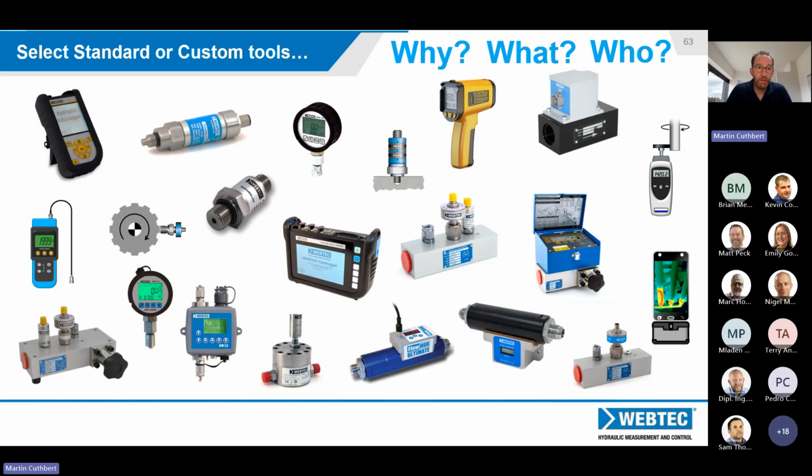We look back at the case drain monitoring. Okay, the case drain is now 10 litres. Is that good or bad? Is it 20 litres? Is that good or bad? So you need to know, what are you going to do? What's the point when something causes you to take action? And for that, you might need to benchmark what the ideal performance is and then be able to compare it.